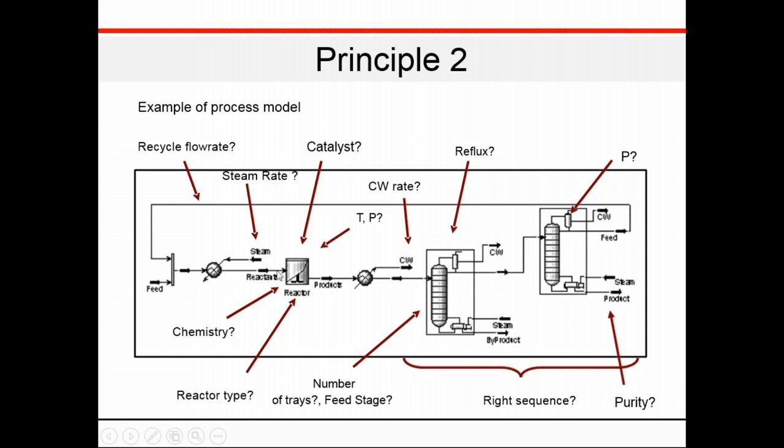From the heat exchanger, you can see steam entering. That's to help us increase the temperature of the fluid. Now, what is eventually entering this reactor? This reactor is like a mixer. It is a heated fluid, so it does some mixing there. Catalyst is also added. In this reactor, the temperature and pressure can also be detected using this simulator.